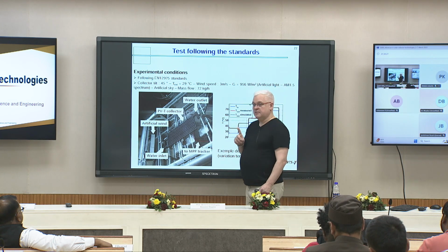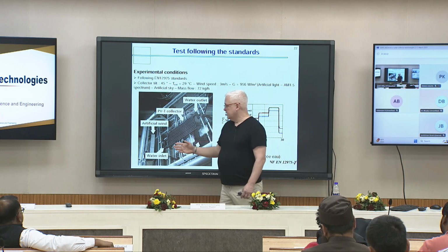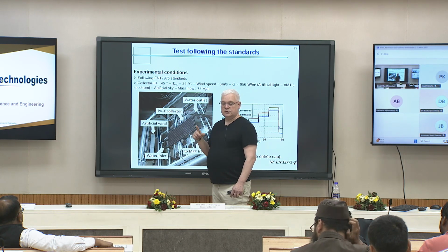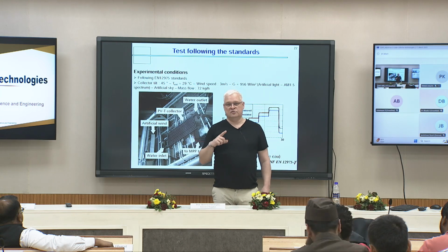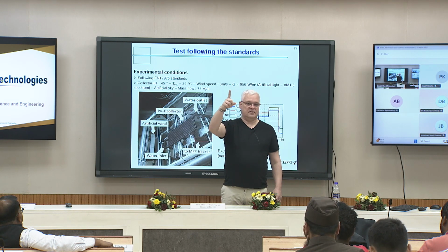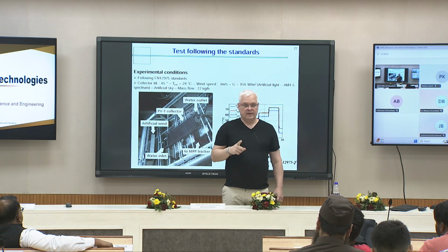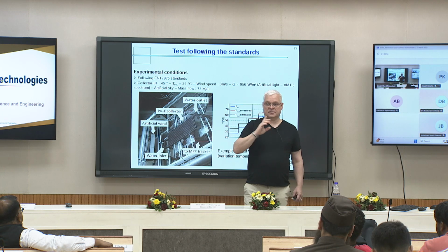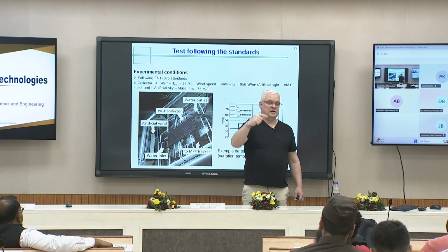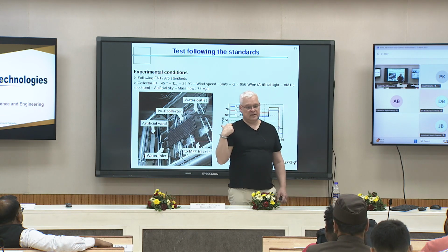But there's one important thing where people testing solar thermal sometimes make a mistake. Your solar thermal collector is heated, and it is very important to consider that it can emit infrared in the direction of the sky, the celestial vault. Okay? It's very important, because if you don't consider that, you will overestimate the efficiency by this test.